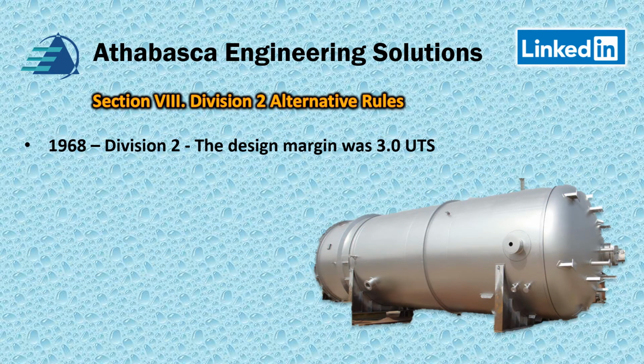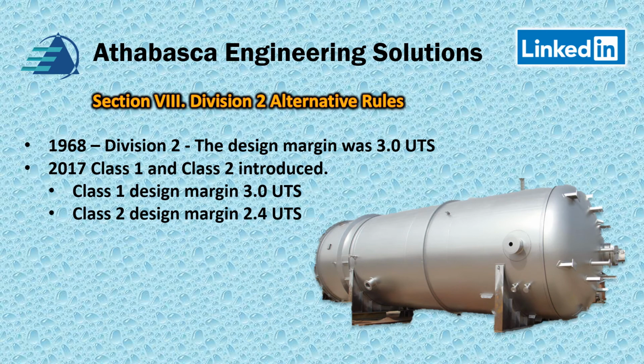Now, in 1968, Division 2 was introduced, and it had a design margin of 3.0 for the UTS value, or the tensile value. And basically, you can see that way back in 68, Division 1 had 4. So they were seeking less wall thickness.